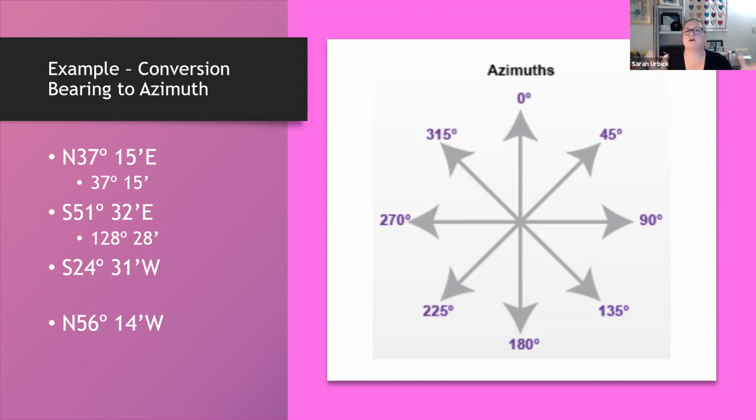So we have 180 degrees. Kenny's absolutely right. 180 degrees is actually 179 degrees and 60 minutes. So if we need to subtract out at that level, we can. It just makes it a little tougher. It's also 179 degrees, 59 minutes and 60 seconds. So if you want to write it out that way and do the math, that's fine. It's not stuff that I like to do in my head. I have to write it out if I'm going to do that. So what's easiest for me is getting it converted to decimals and doing the math that way.